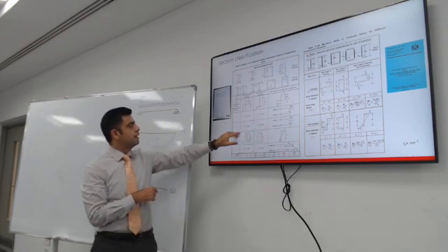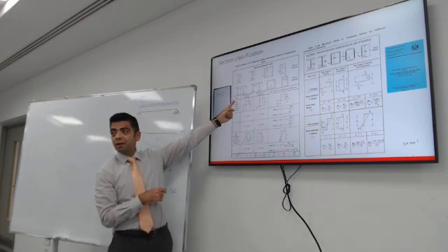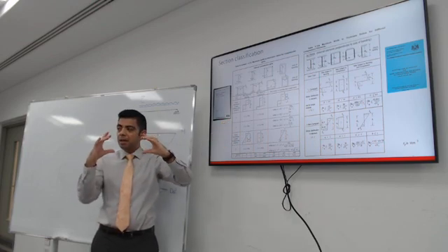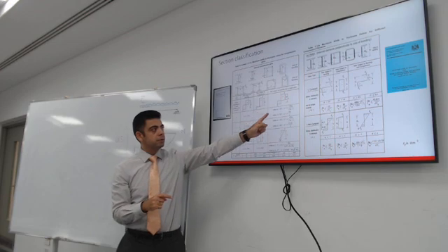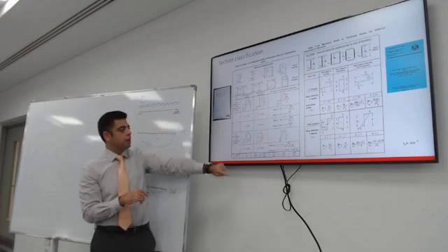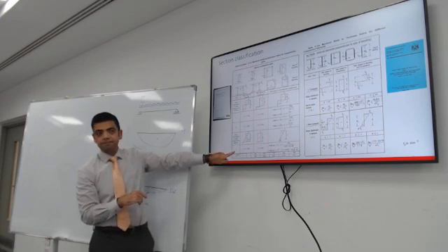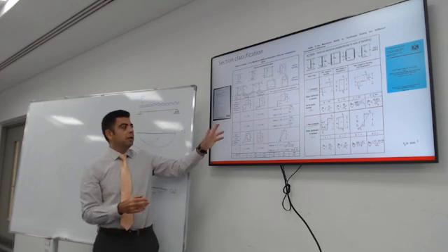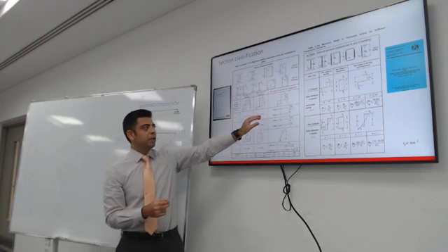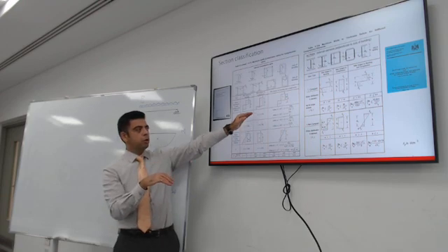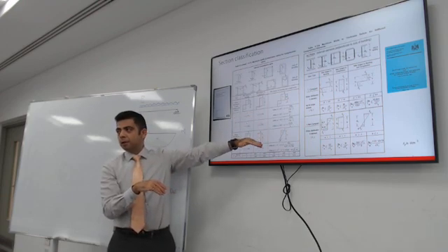For the Eurocode, it says that's the class of the section. If the beam dimensions fit these values, that would be class 1. If it fits the values below, that's class 2, and you have all the way to class 3. I need you to understand how to use the table. Best case scenario, if your section is class 1, it will fulfill these ranges. If it does not fulfill this range, you'll need to check the class below it and below it.